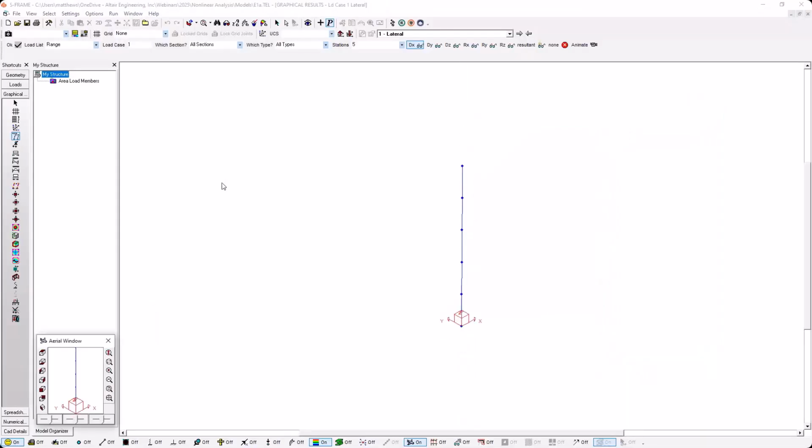And now when I look at my results, I'm going to start with dx, my displacement value here. I can see that my lateral displacement appears to have dropped, actually. It was 2,350 millimeters before, approximately. Now it's around 2,000 millimeters. So we're wondering what happened to this. We're still applying the same amount of load, but where the difference lies is actually with the Z displacement. So you can see now I'm getting about 450 millimeters of displacement, which wasn't accounted for in my linear or